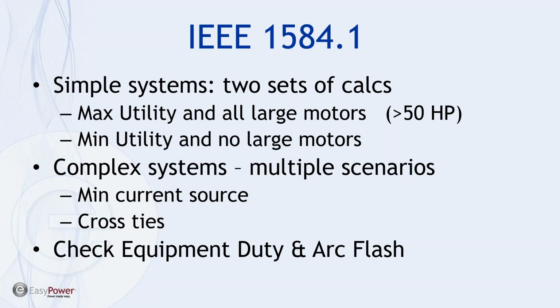Now, if we have an emergency generator, most often when we're in standby generator supplying as the energy source, that will be the lowest short circuit fault current, and consequently the more conservative or the higher incident energy calculation. But if we never intend to run on standby power and do maintenance, then it could be debatable, and it may or may not be appropriate to put on the label. So that's why I say this goes to company policy, and that's something you have to determine internally.